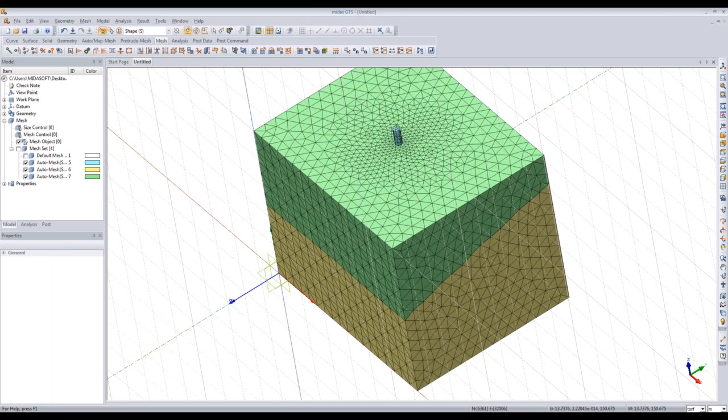The mesh that was created in the beginning was not continuous, right? Because you didn't do any boolean cuts or any embedment. You just put the cylinder in the box and meshed. Now it was not continuous, right? That's correct. This one looks continuous because you did the boolean cut and then you meshed after that.